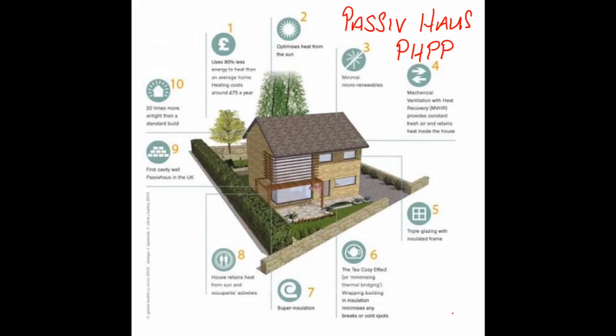It extracts the energy from the air. For every 1 kilowatt hour you put in, for electric is around 15.5 pence, that's at my house, it returns 3 kilowatts of energy. So for every 1 kilowatt hour you put in, you get 3 out.